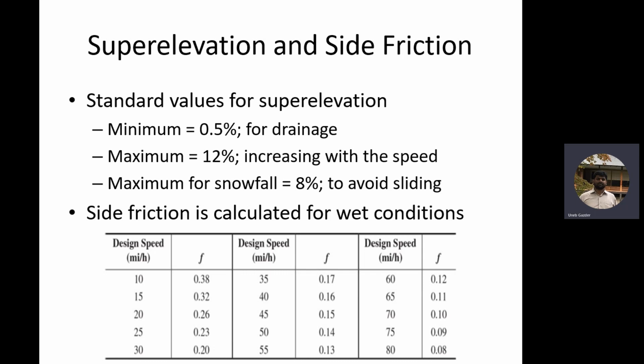So if you are designing the road for a higher speed, superelevation should be higher or lower? Okay, let's vote. Who says higher? The speed is higher, superelevation is higher. Raise your hand. Okay. So the other people are saying superelevation should be lower when speed is higher, right? You didn't see I raised my hand as well. I was giving you the hint. When speed is higher, superelevation has to be higher.